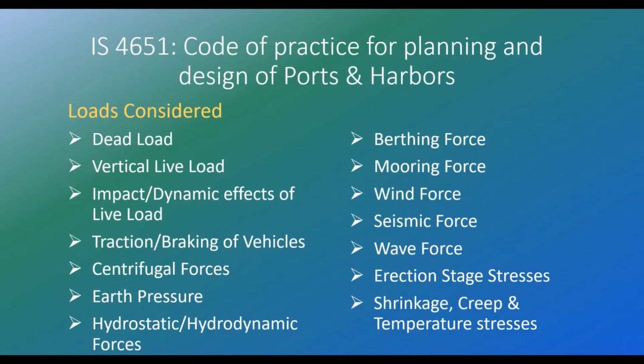This slide talks about a myriad forces that act on waterfront structures. Broadly, loads are classified into two groups, operational and environmental. Under operational loads, we have cargo loads, loads due to crane movement, braking and traction due to movement of goods train. Under environmental loads, we have forces due to wind, seismic and waves. Also, the berthing and mooring forces due to vessels is a separate category. So I'll make a comprehensive video on loadings in the near future. So we'll get a bit better picture of the same.